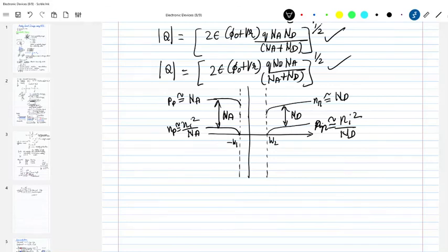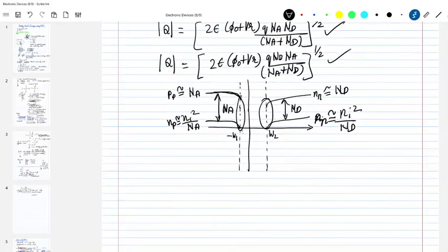Okay, so now this makes sense. This is called the depletion region because it is devoid of, what is it devoid of? It's devoid of minority carriers. It's not devoid of majority carriers. Majority carriers here are still Nd, and majority carriers here are still Na. So this depletion region is not devoid of carriers. It is wrongly taught in class. The depletion region is devoid of minority carriers. They become 0, while the majority carriers are still there to operate. Okay, so this is the carrier distribution.